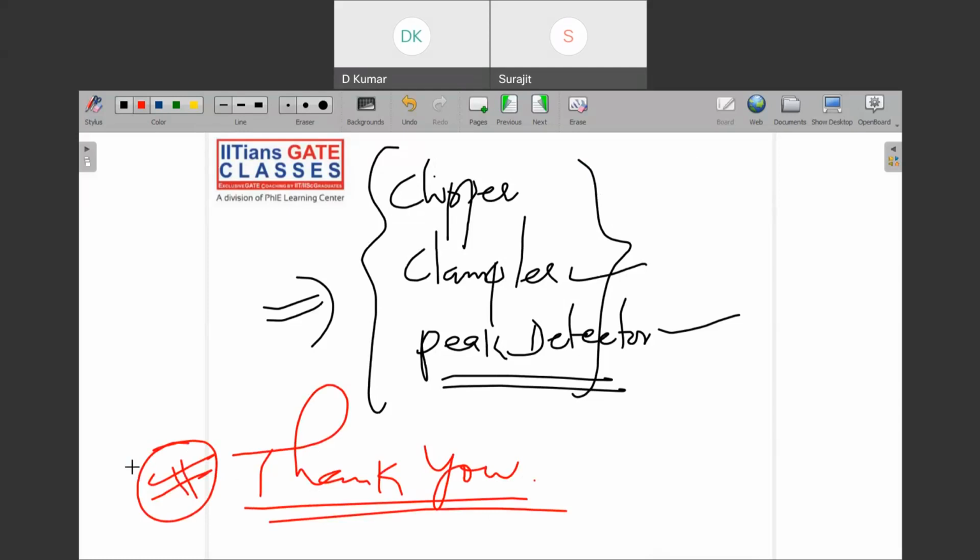Sir, you told me to find the reason why we use an instrumentation amplifier. So what answer have you got? Sir, I checked one video. I don't understand the total meaning, but I understood that in the first stage noise is coming, and because of variation of internal resistance the common mode gain will be increasing somewhat. So we have to increase the CMRR by getting two inverting stages in the differential amplifier, making an instrumentation amplifier. This is what I understand, sir.